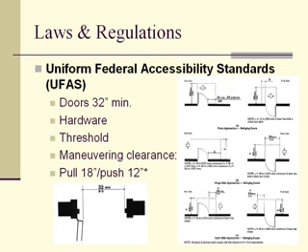There are specific requirements regarding the hardware. It's supposed to have lever type hardware, and also the threshold should not vary more than 1/4 inch vertical in height, and it can go up to 1/2 inch, but it has to be beveled in a 1:2 ratio. Only sliding glass doors, I believe, are allowed a little bit more, but that's not the case in most cities, and especially in Florida. Our sliding glass doors usually tend to have a higher threshold than that, 1/2 inch and 3/4.